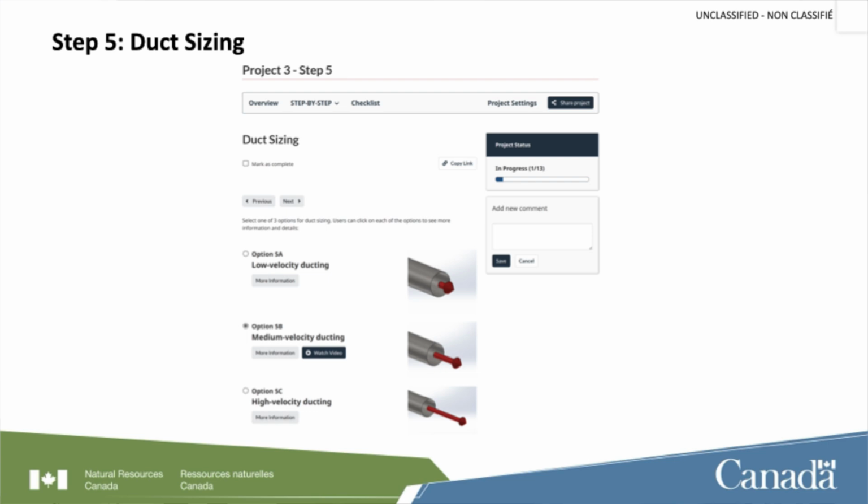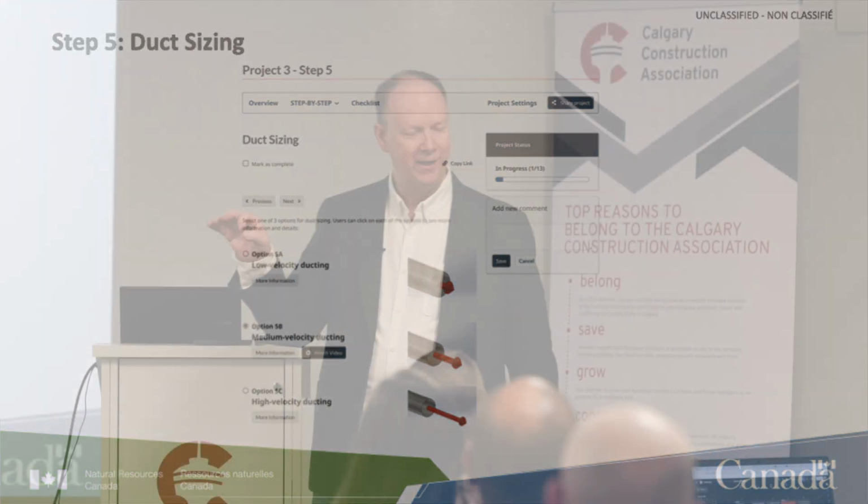Going to a mid-velocity system or a high-velocity system, we're reducing the size of the duct, we're increasing the pressure within the duct. In a low-velocity system, we have our takeoff, we've got our trunk, our supply, and then we've got the supply going to the room. In a low-velocity system, that first takeoff gets the most air. The second one gets the second most air, and so on and so forth. And usually our bonus room, which is at the very far end, it's getting nothing. Just can't even blow out a birthday candle, right? It's a 90-year-old man blowing out a birthday candle.